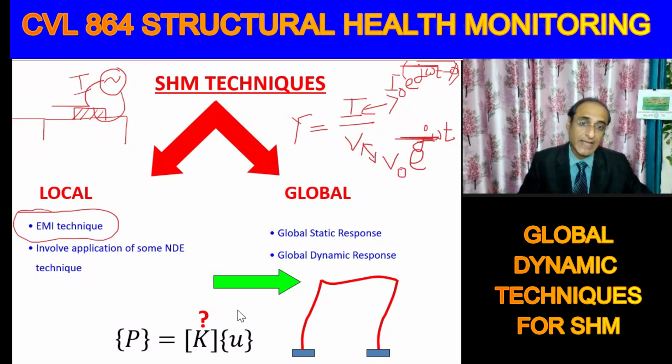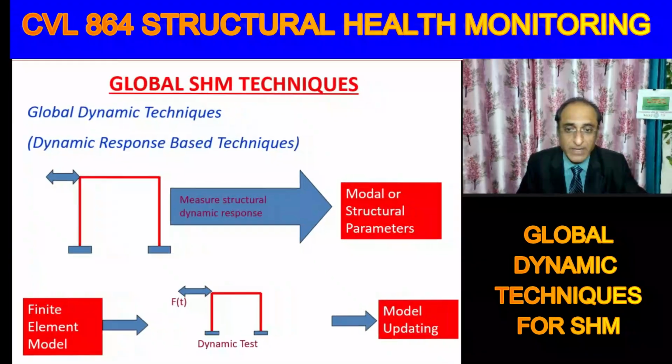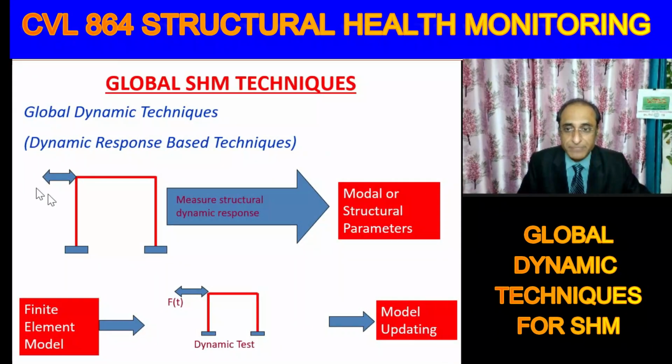Now global dynamic techniques are different. Here, instead of a static force, we apply a dynamic force. Dynamic force application is not very tough. Even if the structure is very huge, we can still excite it into vibrations. We don't need a very high amount of dynamic force. So that's the beauty of the dynamic techniques.